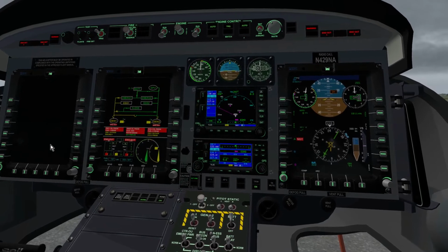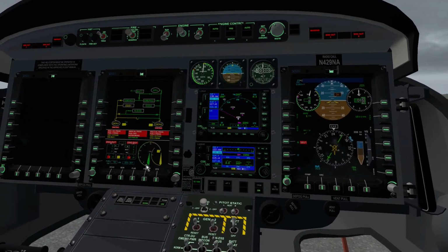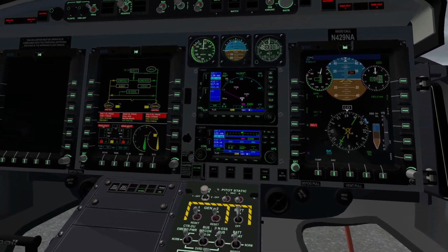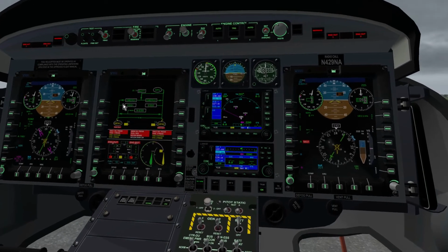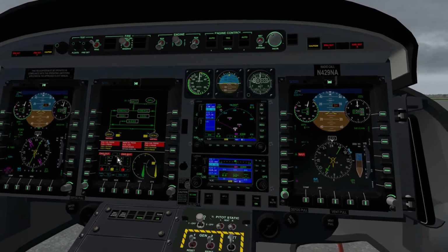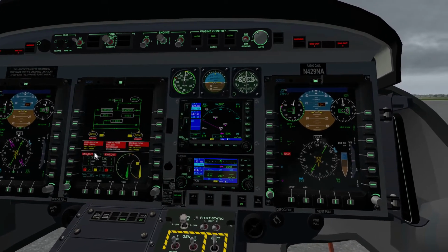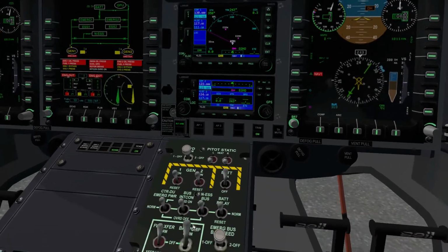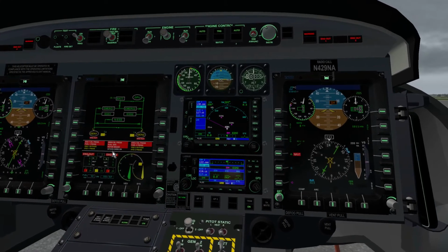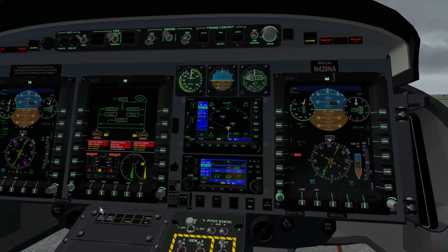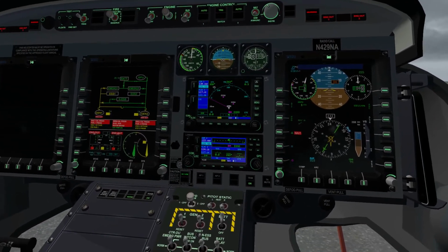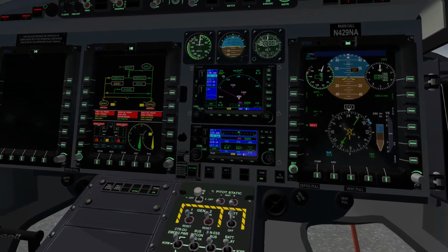As you can see, the left hand display is off, which is part of the left hand essentials, essential number 1. We can connect. We've connected the essential number 1 bus, and you see the left hand display comes up. When you start the generators, this automatically happens, so you don't have to bus interconnect override. Also, you can see in here we've got interconnection override on, and we can switch it off, or on.